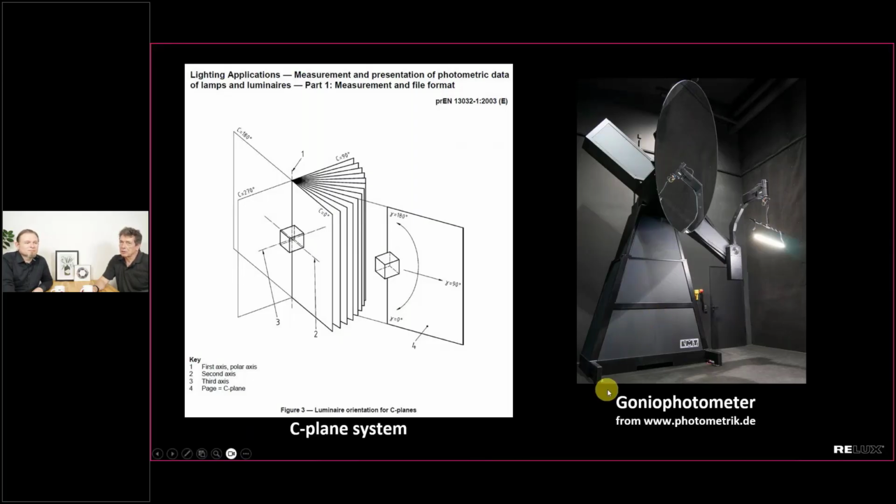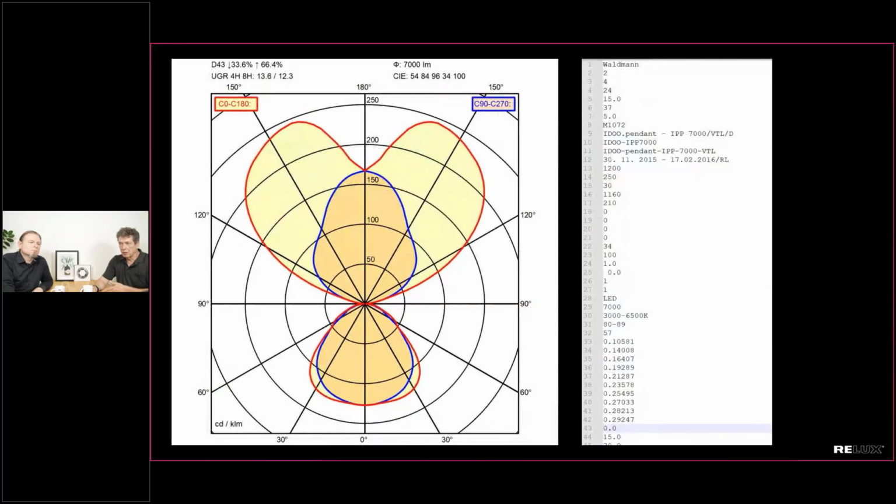The software can normally work with all kinds of files, but for many reasons symmetrization is helpful to identify the aiming planes, the symmetrical planes, and in which direction a luminaire should be aimed or adjusted, especially for street lighting or floodlighting. Then it is very helpful if the file is symmetrized, or it may lead to problems if it is not symmetrized.